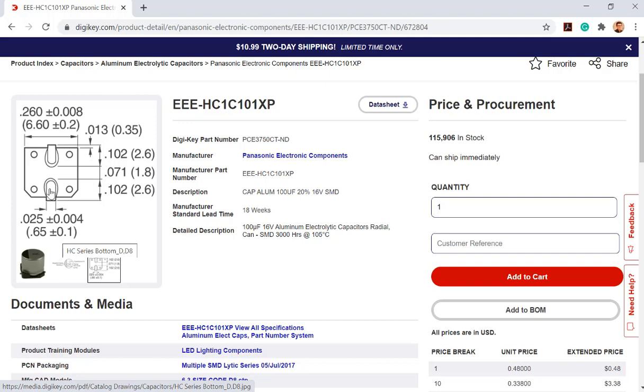And so these ones are 0.65 millimeter. So when you are drawing the pad for these ones, if you are using the 0.5 millimeter grid, you definitely are not going to get something like this, right? Because it's going to be 0.5 millimeter multiples. And you don't have to make it exactly the same size as the pin.